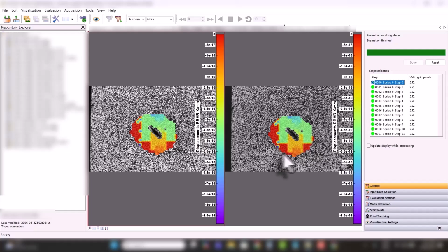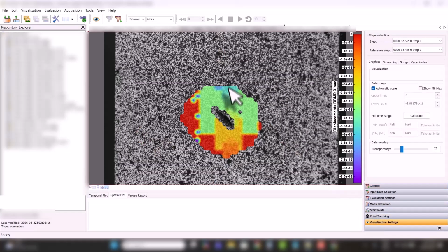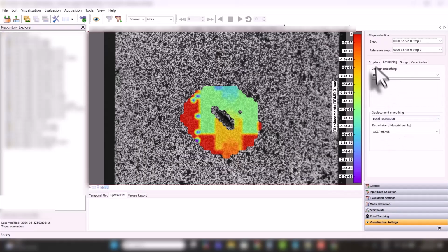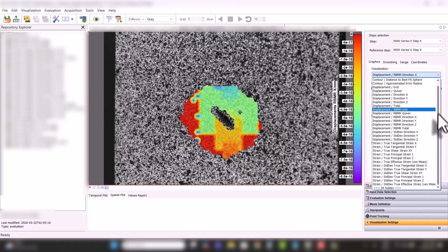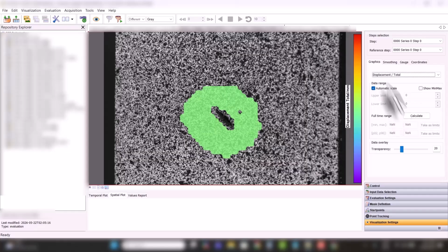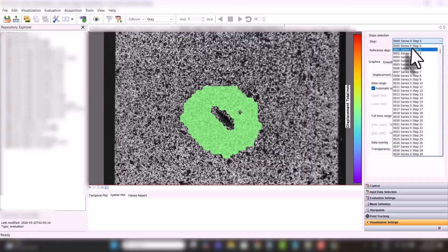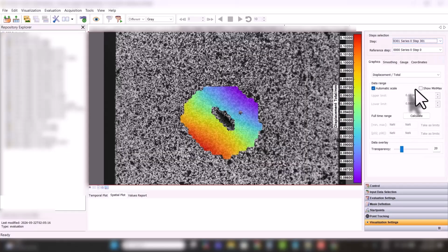Okay, so let's see. This is a weird looking graphic, but this can sometimes happen. I found with these rigid body motion removed directional displacements. Remember, do not let a graphic scare you. The graphics can be very deceiving. That was at step 0 anyway. You want to trust the probe values and look at the precisions.